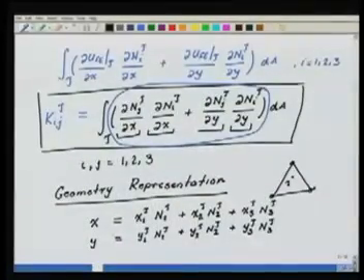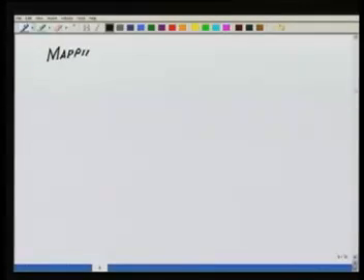Now if you remember, from a computational point of view, it was much easier to work not in the physical element. We could do everything in the physical element, but we decided to map our physical element in the 1D case to a master element. Similarly, in the case of this two-dimensional problem, let us map our physical element into a master element. So let's define a mapping. And how are we mapping? It's a linear map.